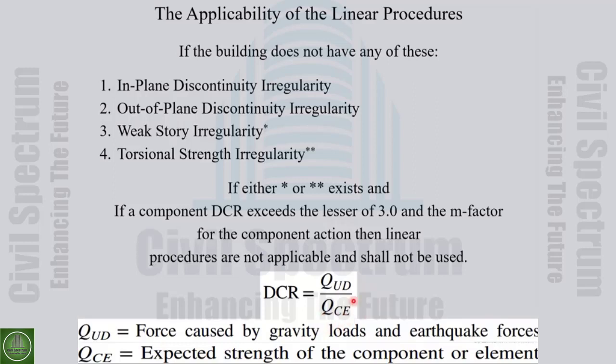For the force control response parameters, the scary ones that are very brittle, we use the lower capacity. But for the deformation control parameters, we use the expected value for the characteristic of the material. Therefore, for the calculation of the capacity, in the evaluation codes, new formulations are not introduced.